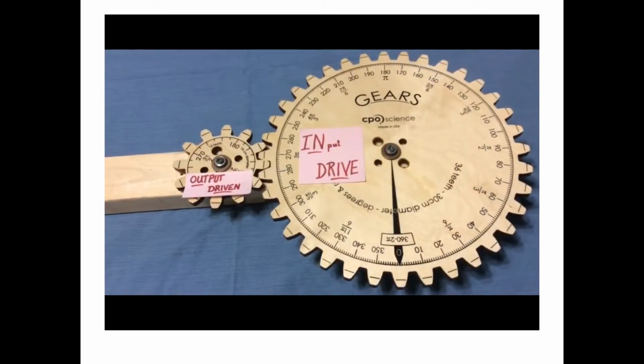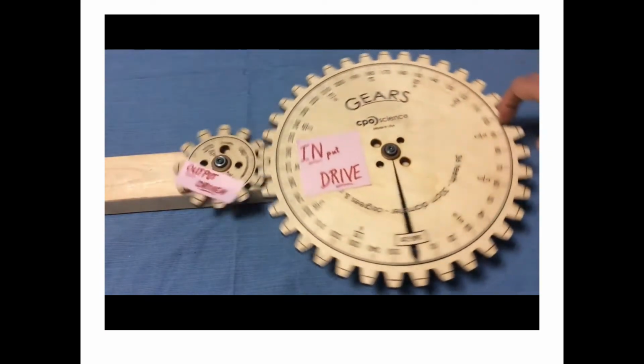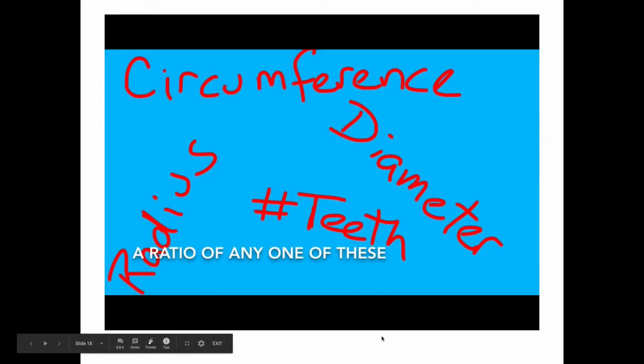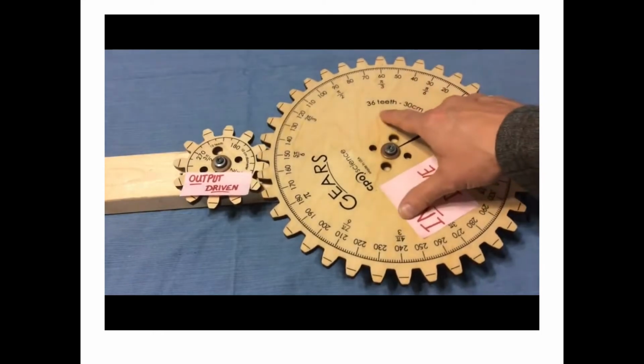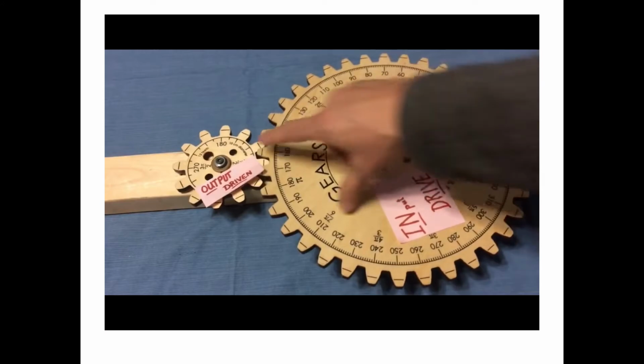When analyzing gears, first, just play with the system. Then clearly identify which is the input, often called the drive, and which is the output, often called the driven. We'll need to calculate a ratio, and you can use either radius to radius, diameter to diameter, circumference to circumference, or often very conveniently, the number of teeth to the number of teeth, because teeth represent circumference.